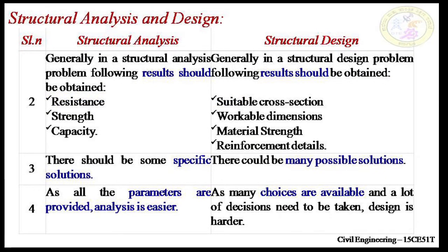Now the results obtained will be resistance, strength and capacity in an analysis problem, whereas in the design problem it will be suitable cross sections, dimensions, material strength and reinforcement detail. There will be a specified solution obtained in structural analysis, whereas in structural design there could be many possible solutions.